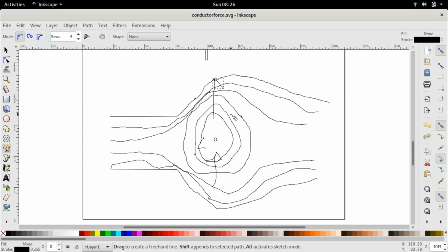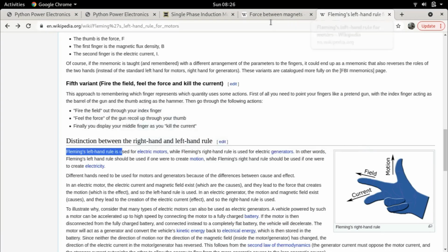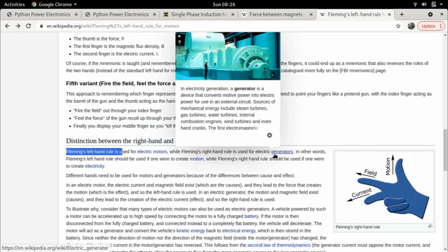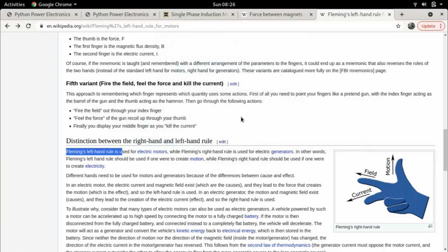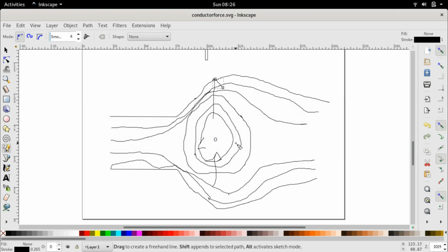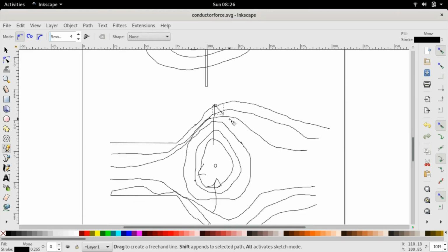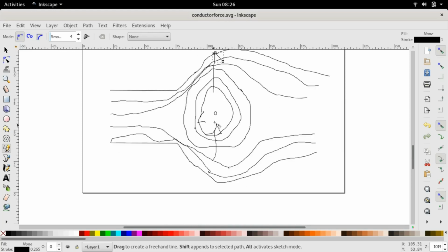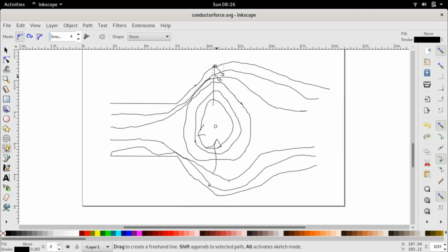And depending on how the magnetic field will look like, we can always determine what is the nature of mechanical force. So if we take together all possible cases, we can always find out what will be the mechanical force, and this Fleming's left-hand rule is basically nothing more than just a convenient law, so that we don't have to draw these flux lines every time, right? We can just use the law. But the law is basically eventually just a conclusion of this interaction. That's all there is, right?